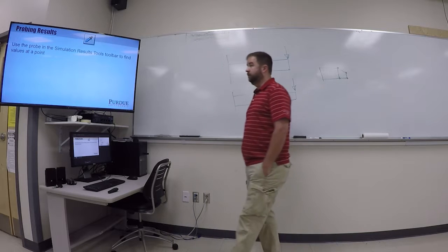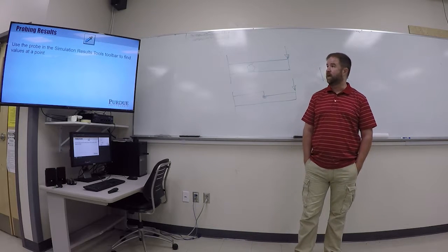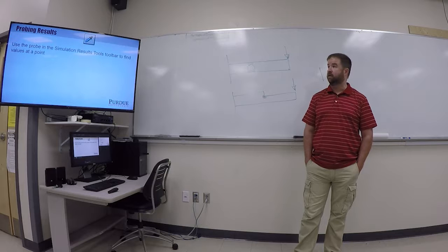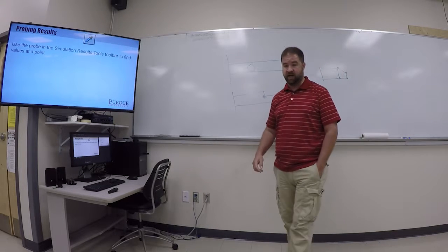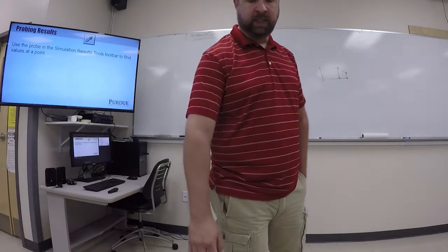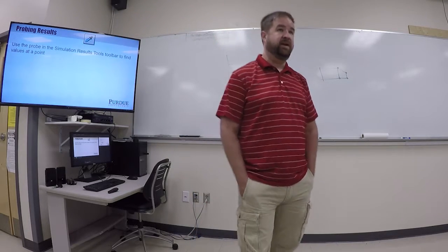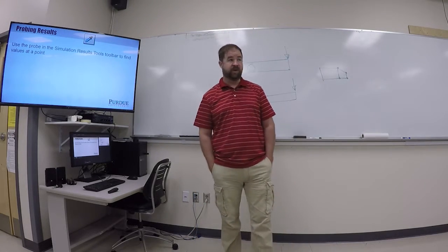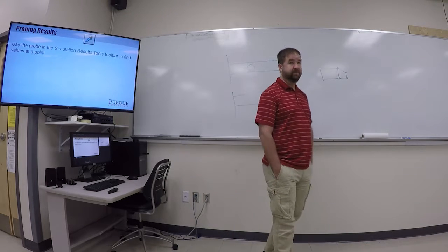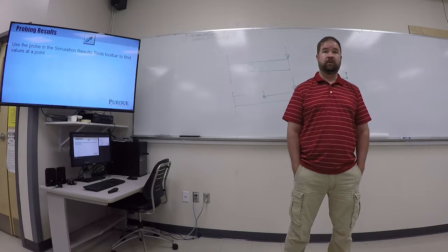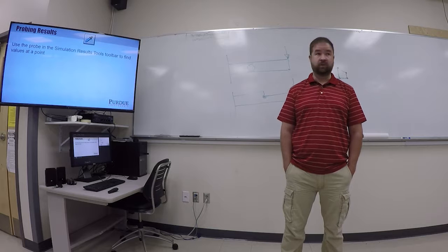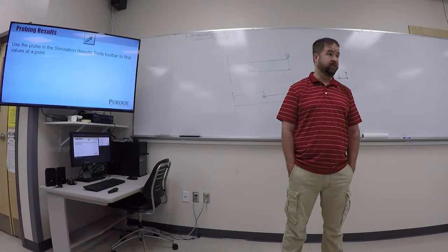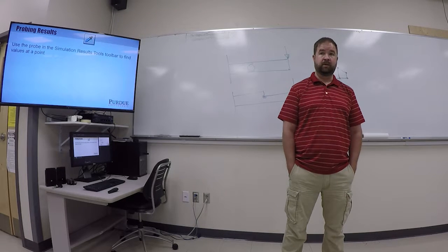All right, and I've talked about this with a few people, but I had another question about it, so I put it in here to make sure that you're aware of it. Some of these assignments, you are going to need to find the value of stress or the value of displacement at a particular point. And the tool that allows you to do that easily in SolidWorks is the probe tool.